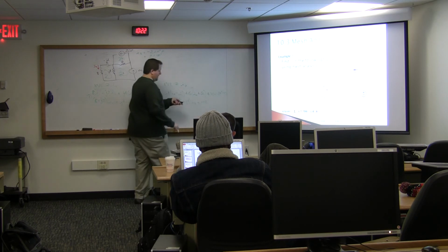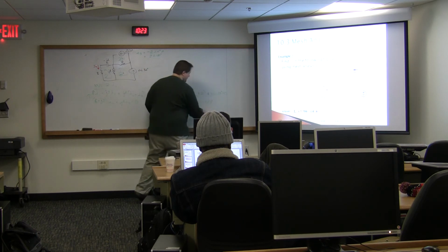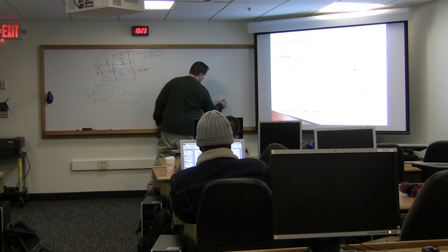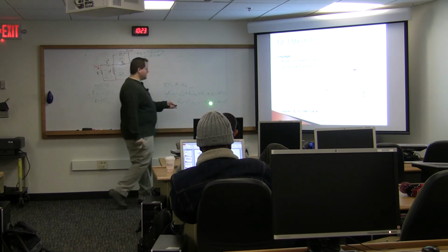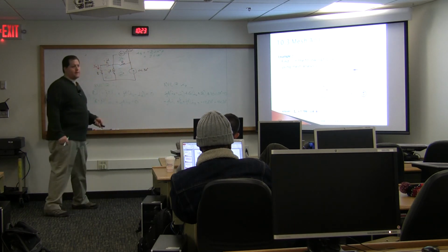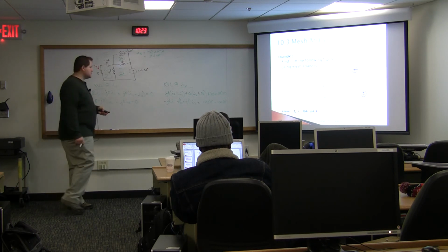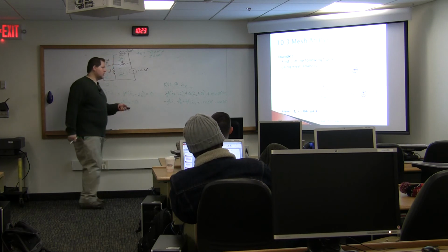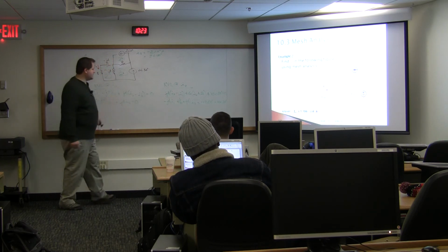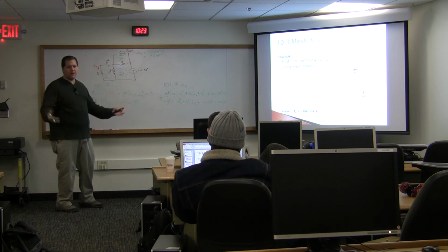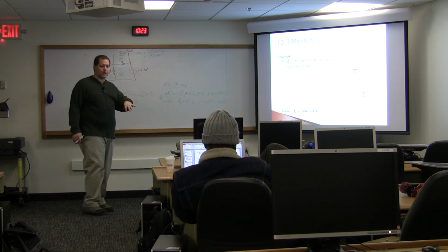Negative 12 is negative 12, it's got a phase of 0. Minus 10 phase 30. We're going to need to combine those two in MATLAB, so you do need to be careful of that. Don't lose the phase. Okay, so now I have my second equation. So 2 equations, 2 unknowns. Again, put them in matrix form, drop them in MATLAB, solve it.